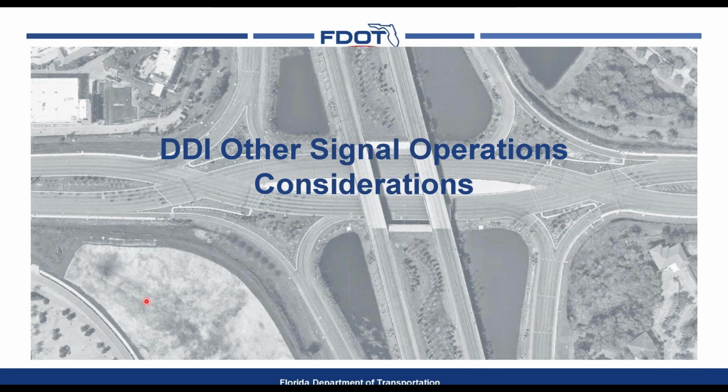Yeah, maybe. Again, the bicyclist through the interchange core is going to be to the right of the vehicles at all times, which means they'll be on the inside. To me, it's more that question of when the bicyclist's go, no go decision is as they're coming up to the intersection. Again, they should be visible. Certainly the bigger concern to me is the bicyclist being able to clear what Randy referred to as that T2. So clearing, say, that right turn ramp, where that right turning vehicle should be able to see the bicyclist. Actually, the bicyclist is on the correct side of the vehicle that's potentially shielding it.